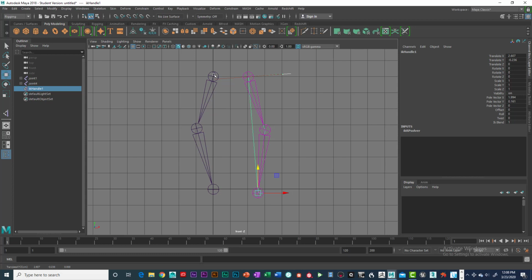You want the arm to rotate the right way. So that's how you do preferred angles. That's why you set up your preferred angle when you're creating your joints in the first place. So when I do add an IK joint system, and we'll talk more about that later, that's why we set a preferred angle. Okay, and that's it for this little tutorial for Module 1.